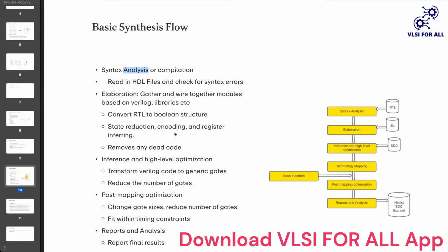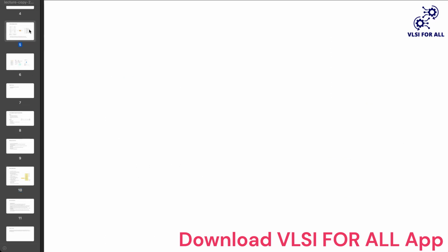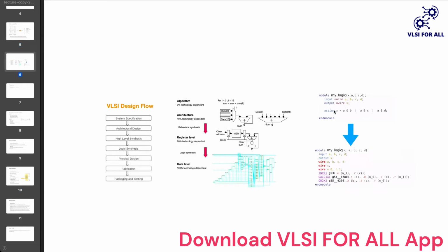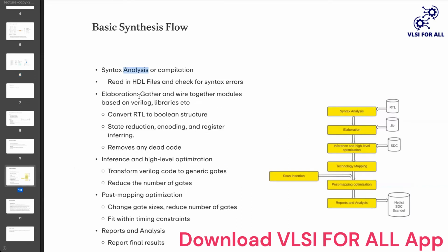And if there is any dead code, sometimes you have these modules, right? And you have some code written within the module and endmodule. Sometimes I might define an empty module thinking, okay, later I might add something to it. But an empty module is useless, right? As long as it is not used, it is useless to have it in the Verilog code. So the synthesis tool also gets rid of the unused modules or the unused Verilog code as part of the elaboration itself.